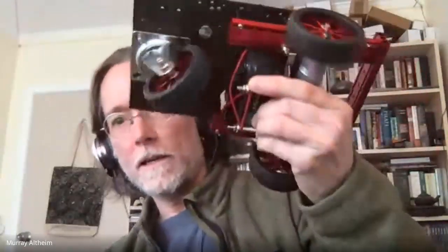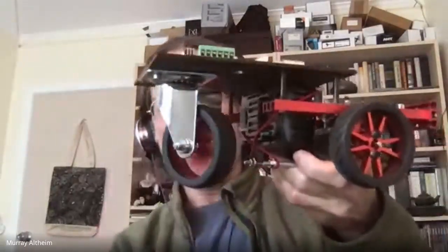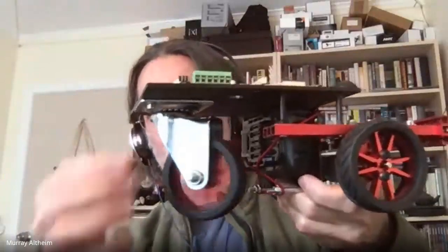It's mostly a test robot, and it's basically got the OSEP motors, and it will be a dual differential drive with another smaller 12-volt Makita battery. But it's mostly a test robot. I managed to mount one of these nice OSEP wheels onto a caster, so that works pretty well. That's just one of the larger, the 2.9-inch clear plastic casters from Robot Shop that I drilled out the center of and then mounted the OSEP wheel on, and it has a bearing of its own, so that works pretty well.